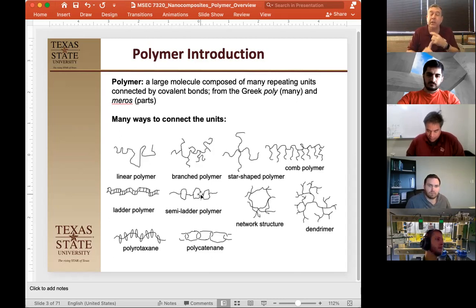They tend to be very rigid, very tough, very poorly soluble, but because of that structure, they are very durable and highly useful for high temperature applications and places where you need something that has a great deal of rigidity and/or strength. Okay. And then there are some that are semi-ladder, meaning they're still soluble, but they have that kind of linking of 2 different polymer chains together.